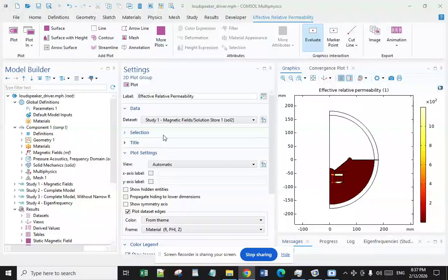The challenges and disadvantages. The disadvantages of electromagnetic compared to piezoelectric UT can be summarized as follows. The first one is low transduction efficiency. Electromagnetic transducers typically produce raw signals of lower power than piezoelectric transducers.